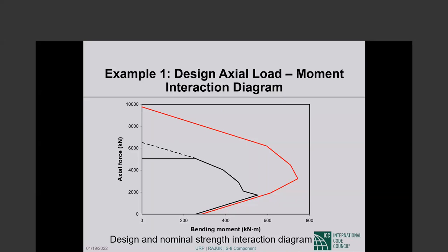And then the last thing that I would say is about column design. When we design a column, looking at the loads and a whole lot of other things, remember, we design a column stack, not a column. And we do not design one column stack, we design many column stacks.